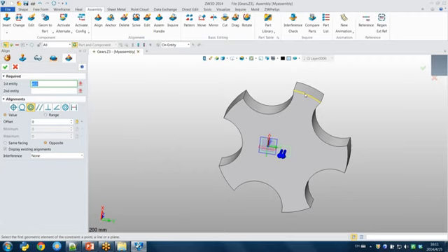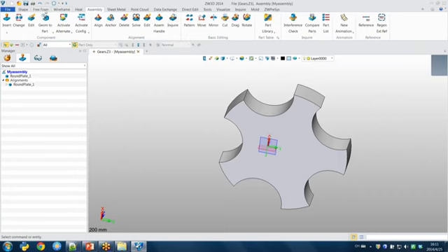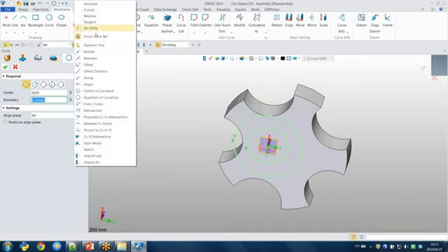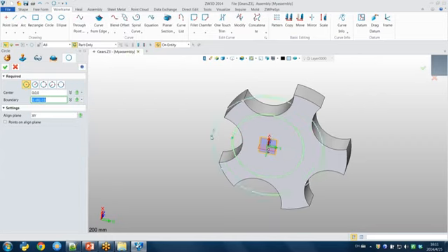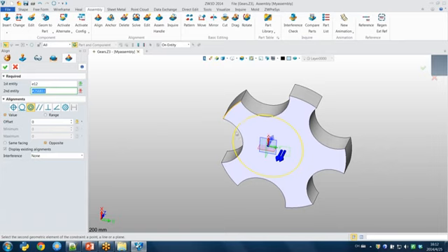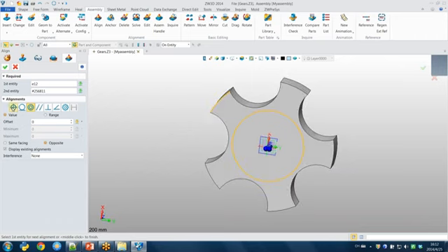If I want to put the part in the center of the direction, I need to join a curve. Okay, join a circle. So I join a circle, put them aligned on the XY plane. So I make alignment, this curve and the circle. Okay, move them with the coincident. Oh, this one must be set in concentric.